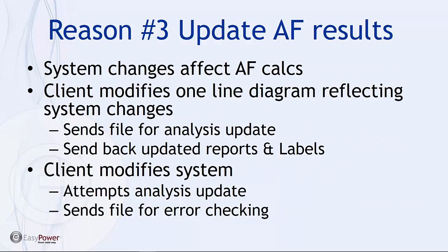Then we go to reason number 3, and that is, if I had, as a client, the database, I do make changes that affect my ARC Flash calculations. Having the database allows me to make changes and then send that file back to my engineering resource for updating the analysis, and then in return I receive updated reports and labels, and I'm able to maintain NFPA compliance with just a modicum of effort, again because I have that database to communicate back and forth.